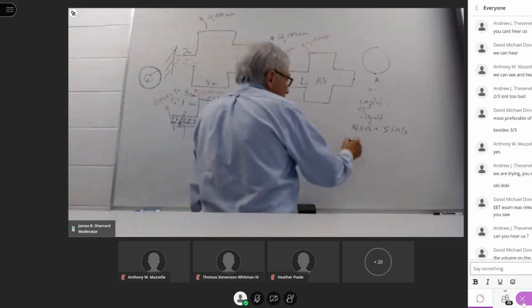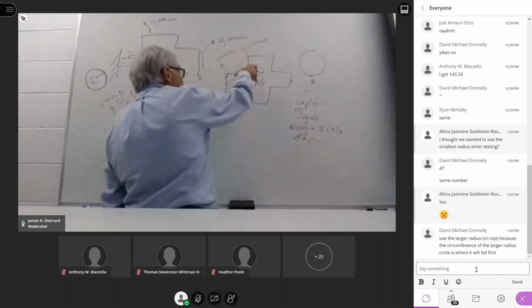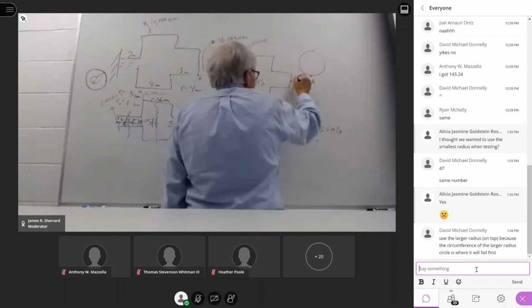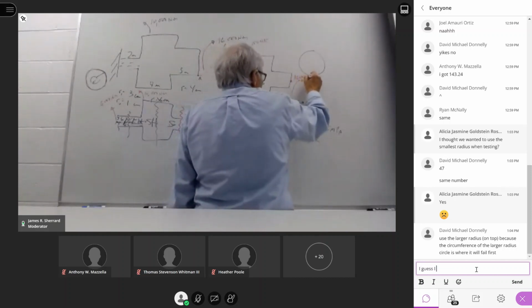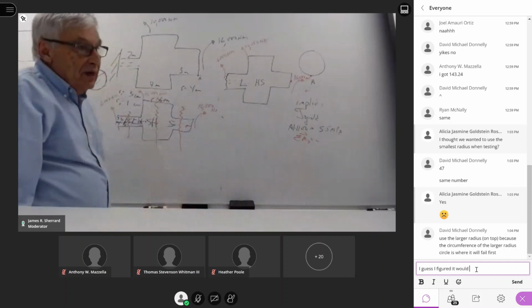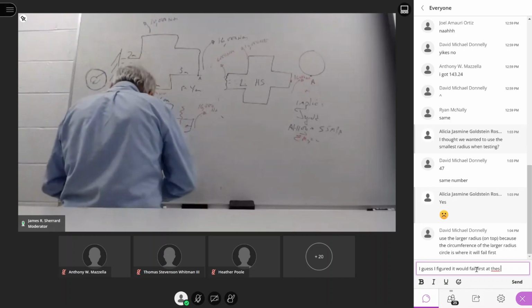Again, this is sum of moments around the x-axis, has to equal 0. So the counterclockwise have to equal the clockwise. So this value is, again, 16,000 Newton meters. Now that I have that torque that exists in region 3, I can go back and do my calculation.